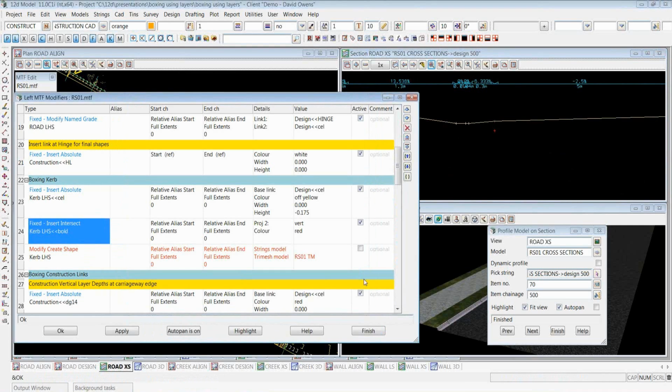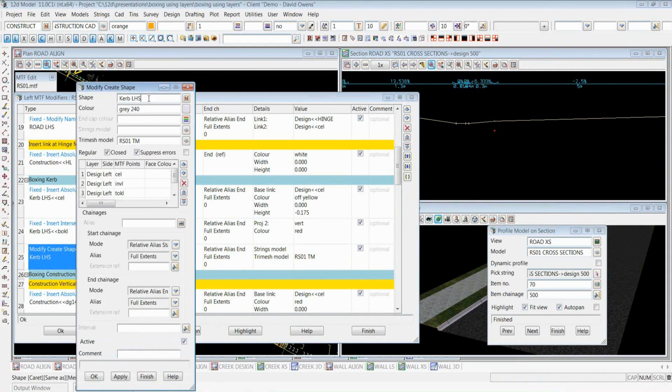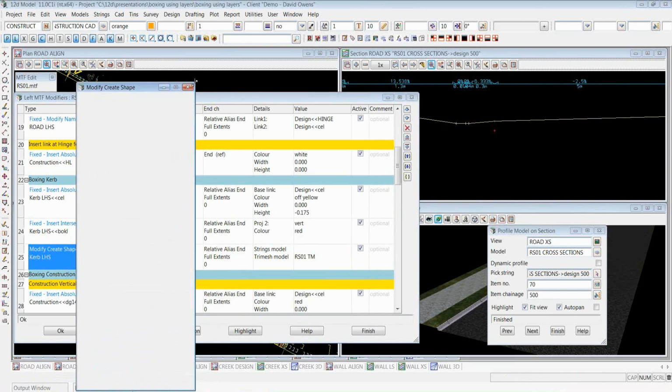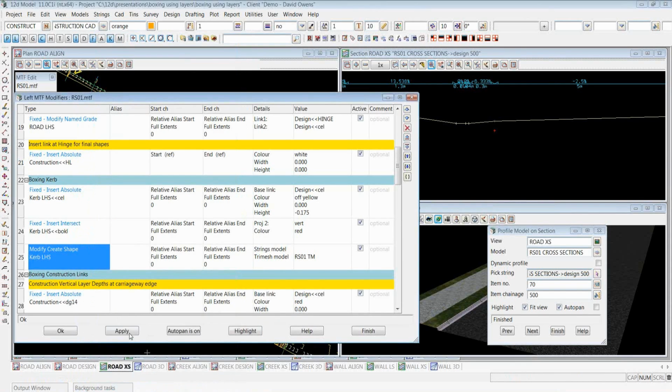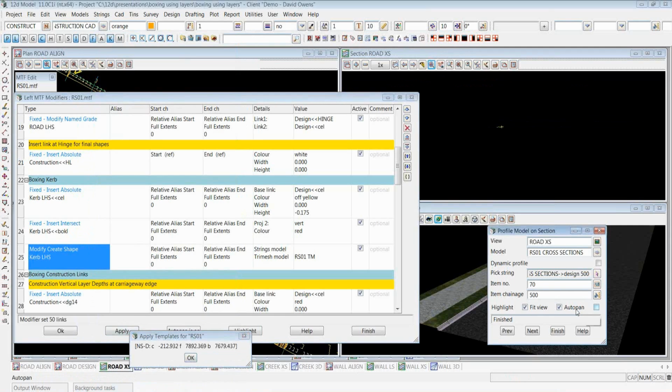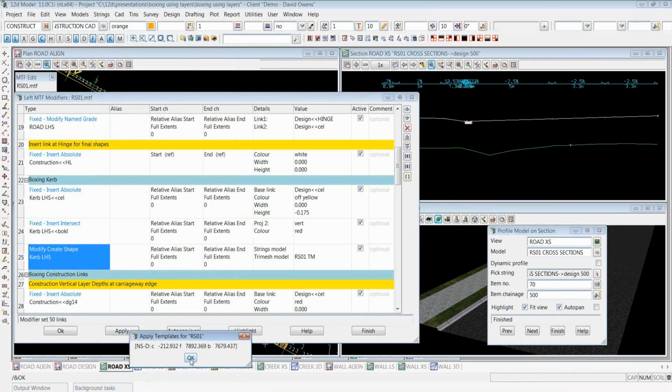And then with our shape commands, it's simply a case of joining all those points together. So we've got points in our design surface, from the carriageway edge, inverted curve, top, back, and then down to my new points in my curb layer, again, back of curb and carriageway edge. Again, notice the recycling of names so I know which point lines up with what. And simple apply.